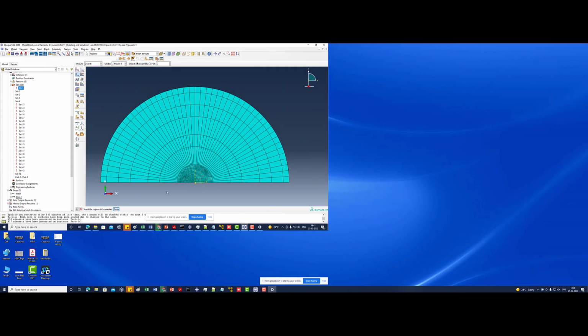So now we have got this proper mesh, and we know that these things are at certain angle. The outer boundary is divided into 50 pieces, right? We must have 50 number of elements on the outer boundary. Do we have them?